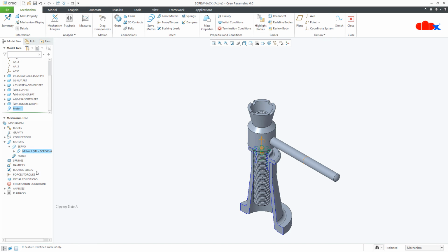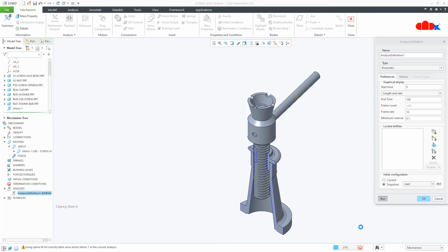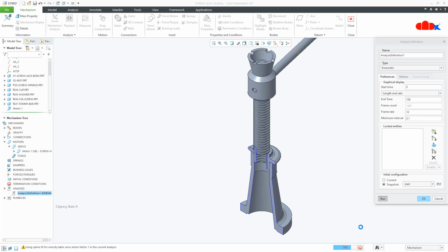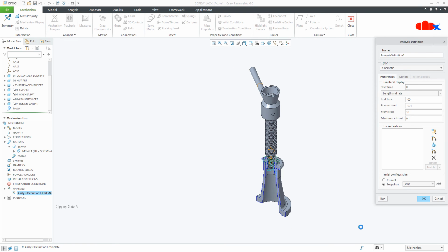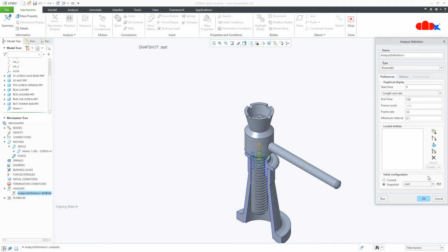Now let's update the animation, and for this you edit it, and here these things you let it be as it is and just go for run. Say yes. Now if you see, your spindle gradually increases, then constantly rotates and then gradually decreases, but it is going out of the body. So let's make it 50. Once again run it. Say yes.